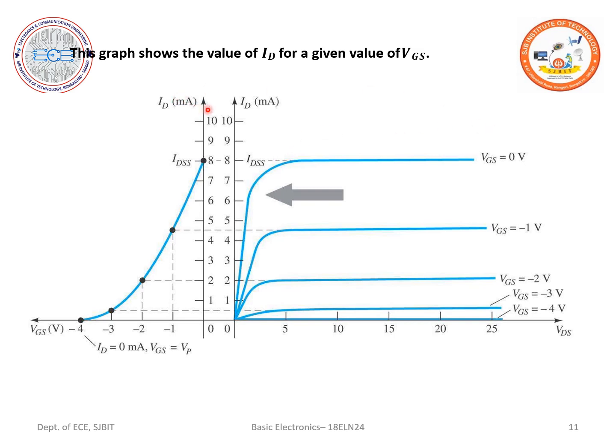Similarly, for the drain characteristic, we keep our VDS as a constant voltage and vary the VGS. We already know that when we vary the VGS, we make it lesser than 0, right? It is always lesser than 0. Where VGS reaches the pinch-off voltage, what is going to happen in the pinch-off region? As and when you decrease your VGS, we can see our IDS is going to become 0 amperes.